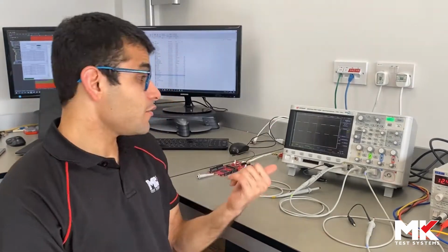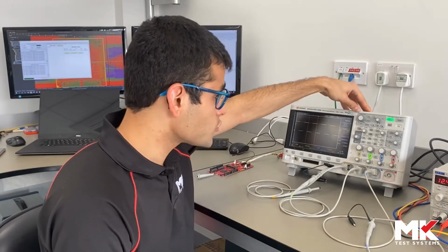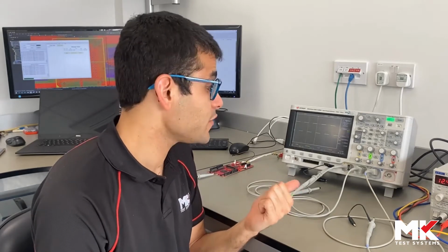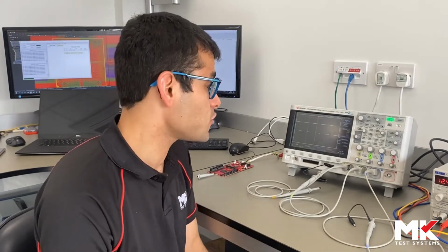Moving to tip 2, which is cursors. One of the cool things about this oscilloscope is that it has a built-in signal generator, which we're going to use to display a square wave. Because I set up the signal generator, I know that the output is 1 kilohertz and the period is 1 millisecond, but the tricky bit and the cool thing is to discover that using the scope.